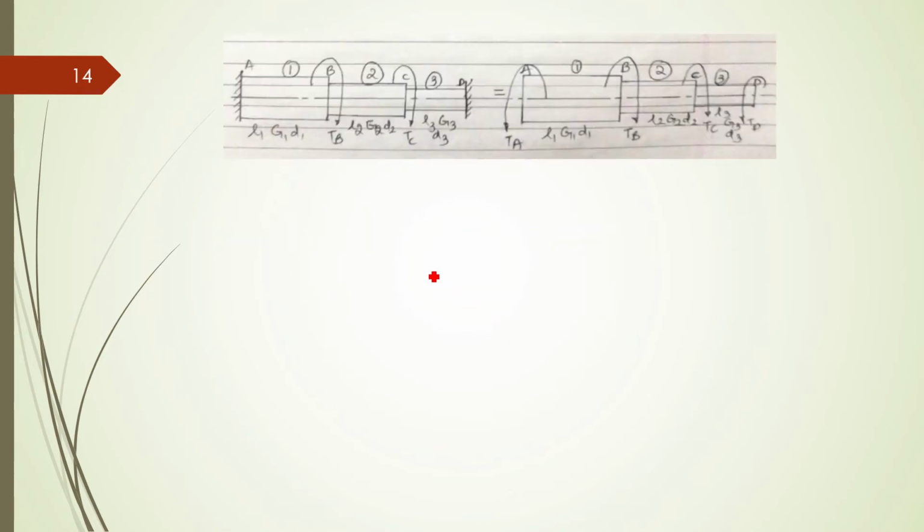Now let's talk about another case over here. This is my second case, a shaft wherein we have 3 attached shafts in series and they are between 2 fixed ends. So this is the FBD which I have drawn. At end A, I have assumed a torque TA which is of resisting nature, and at end D, again there is a resisting torque TD. Now TB and TC values will be given in the question. So let me assume that TB is clockwise and TC is clockwise. That is given to me, and TA, let me assume this as counterclockwise, and TD again as counterclockwise.